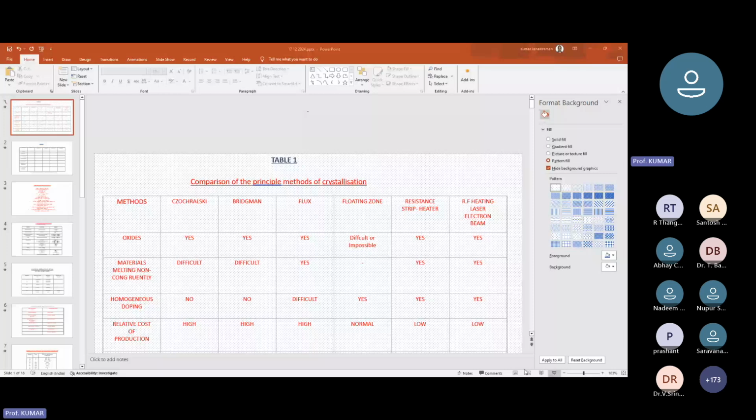So there are various factors of growth parameters. The melt composition is one of the critical parameters, which can in turn affect the dislocation density. It will also affect the dopant levels. As I told, if I have excess of arsenic, I can create a mid-gap level, which is known as EL2, and it can certainly affect the mobility, which is very, very critical for device fabrication. It will also create what is called a microprecipitate, and it will also